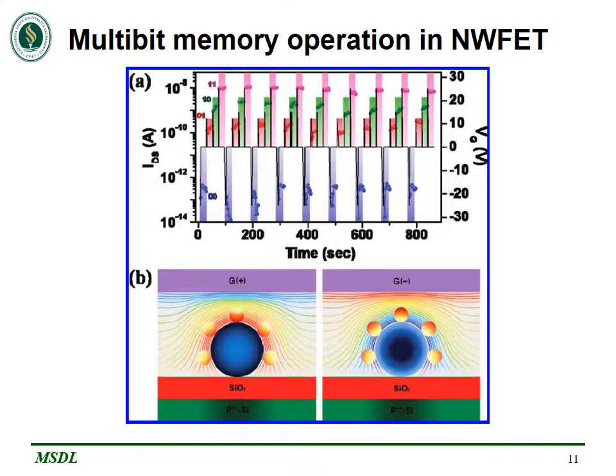Figure A shows the switching characteristics of a device with a top gate structure measured with VDS equal to 0.1 and VG equal to 0 volt, clearly showing that the ferroelectric field effect transistor functions as a 2-bit memory with 4 different conductance states defined as 00, 01, 10, 11 after the application of gate voltage pulses of -25 volt, +12 volt, +15 volt and +25 volt respectively.